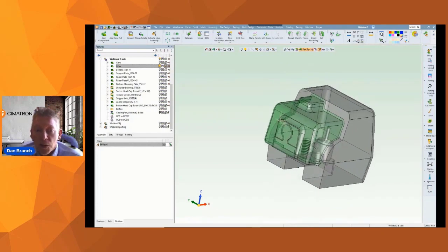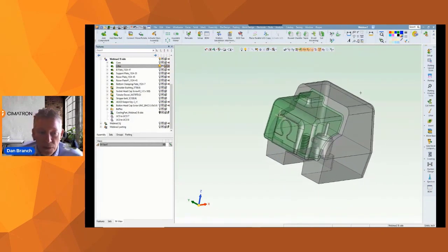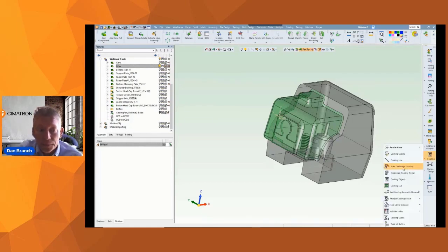Conformal can get water passageways much closer to the part surface. It can get them into small areas that drilled water lines just can't reach. And yeah, it does mean that the component will have to be 3D printed. But we've got partners now, even like DME, that can provide that surface. So it's really not such a limiting factor. And if you haven't seen the quality of a 3D printed metal part lately, I think you'd be surprised at just how dense and how pure they actually are.